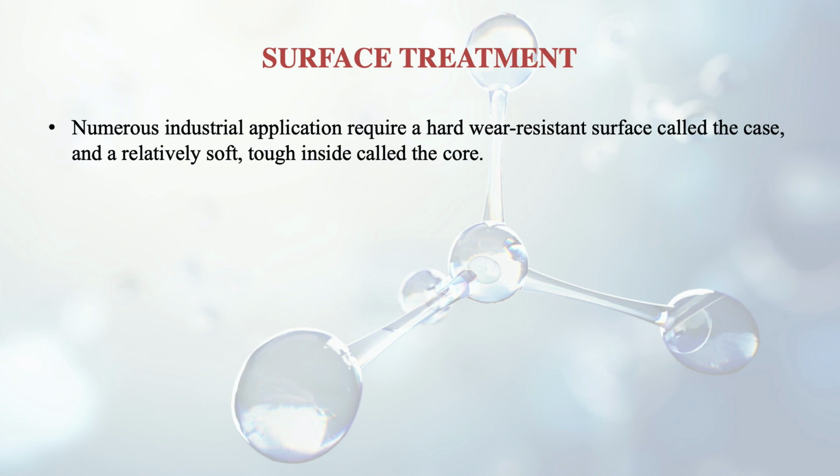So what is surface treatment actually, and why is it needed? There are numerous industrial applications which require a hard, wear resistant surface, which is generally called the case, and inside we need a relatively soft, tougher material, which is known as the core. For that purpose we do the surface treatment.